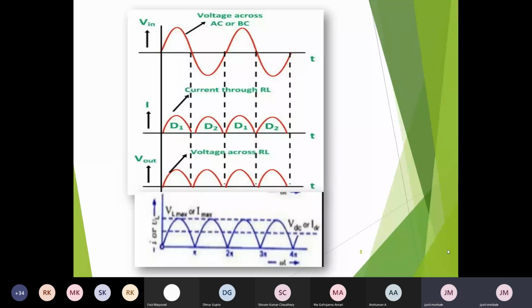इससे related question paper में question आएगा, explain the working and the construction of full wave rectifier with waveform. So you need to draw the circuit diagram, explain the construction, its working for the positive and negative half cycle, and these waveforms are important. You need to show which diode is in on state and which one is in off state. ठीक है, current and voltage waveforms are same.